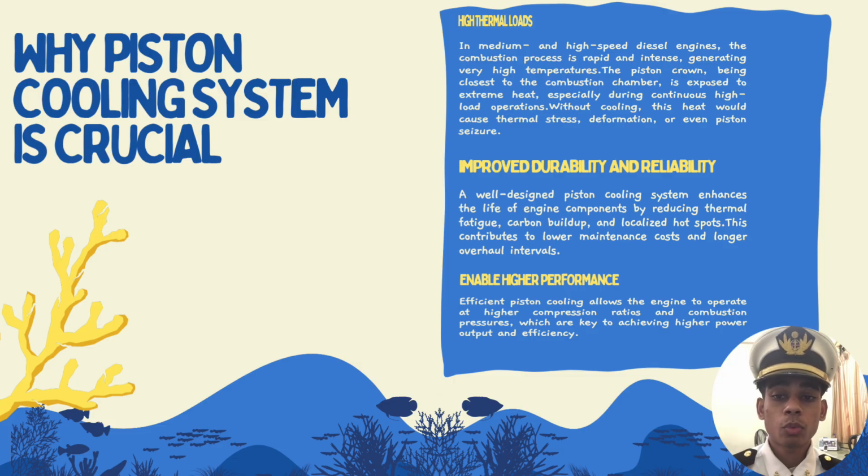Here I'm going to talk about why the piston cooling system is crucial. Firstly, high thermal loads. In medium and high speed diesel engines, the combustion process is rapid and instant, generating very high temperature. The piston crown, being close to the combustion chamber, is exposed to extreme heat, especially during continuous high load operation. Without cooling, this heat will cause thermal stress, deformation, or even piston seizure.